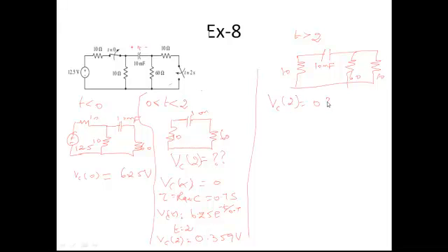for this particular circuit. And you have to find out what is Vc of infinity for this. What will be Vc of infinity? As usual, there is no external source connected. Therefore, all the energy will get dissipated. So Vc of infinity obviously will be equal to 0. So as usual, you have to find out the R equivalent. Now R equivalent is nothing but 60 ohms in parallel with 10 ohms plus 10 ohms.